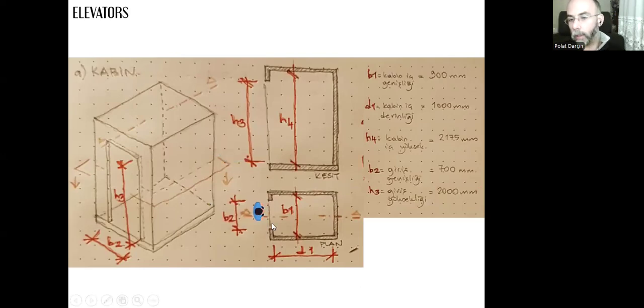And the person can be using a wheelchair. Again, the sizes will change now because now he's sitting, and there is this width of the wheelchair, and if he's using it with his hands, then there will be his hands pushing the wheels on the sides. So 90 centimeters is not enough. We need to increase the width of the doorway accordingly. It needs to be at least 1 meter and 10 centimeters for this type of wheelchair or bigger.